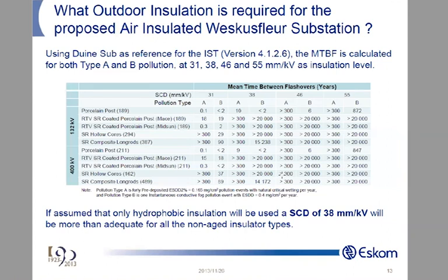The American studies were done where the insulators at 220 kV were not fitted with corona rings. So those insulators were overstressed, and those insulators are failing now. And there's a major replacement, and now they're going to go back, or actually move towards glass discs, which suits certain suppliers.